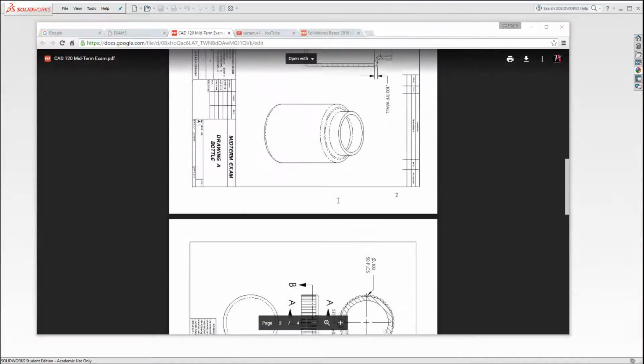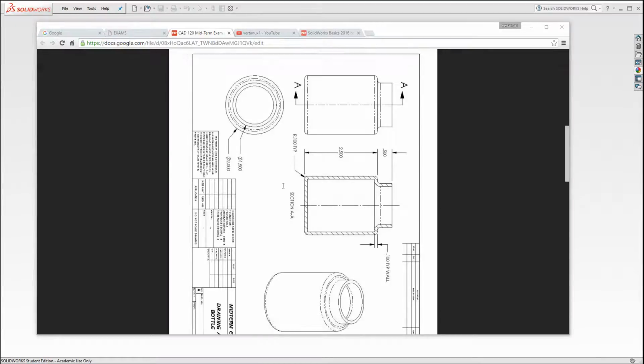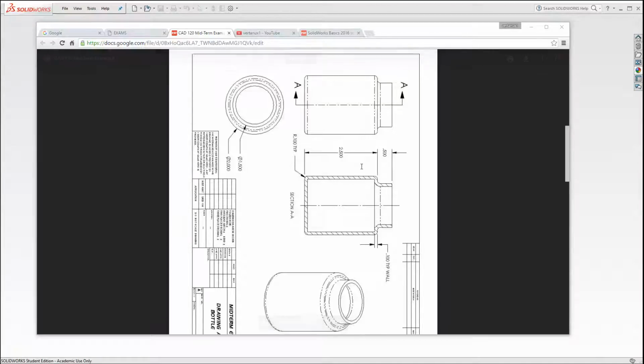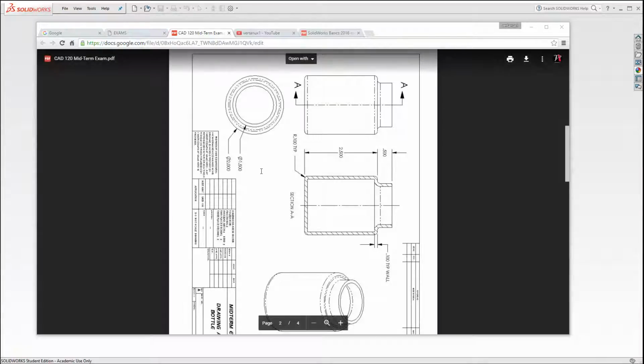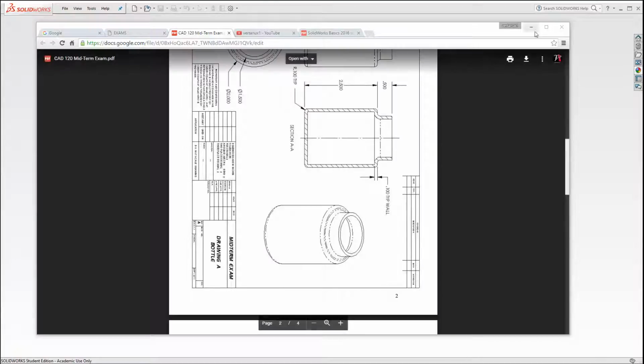So let's begin. First of all, the bottle is a very simple design. Again, this is almost like a widget bottle just to get the concepts down. So as you can see, it's a 2-inch diameter, 2.5 inches in height, with a 1/2-inch height neck, and the neck diameter is 1.5, and it's shelled out at 100 thousandths, and it has radiuses of 100 thousandths.